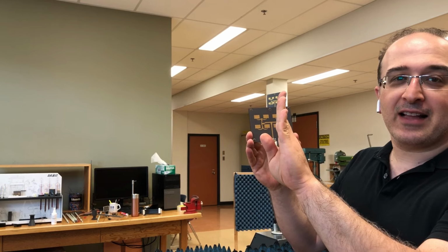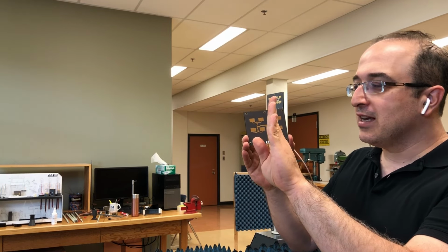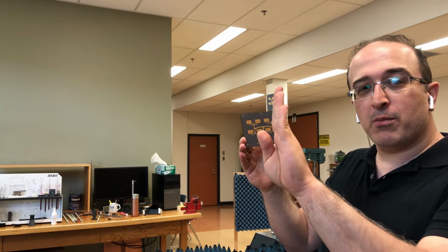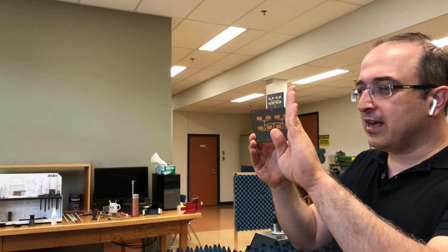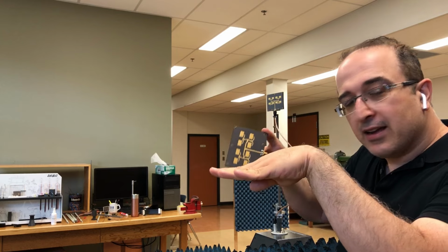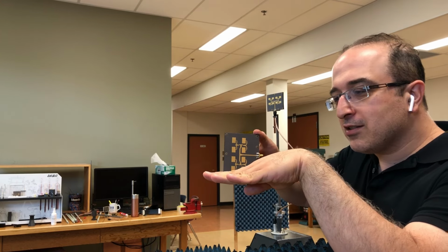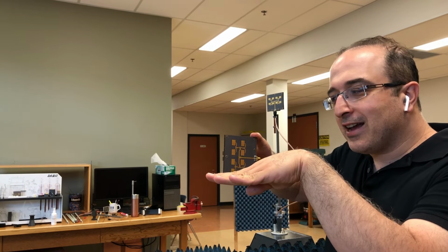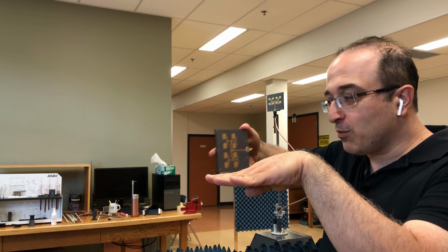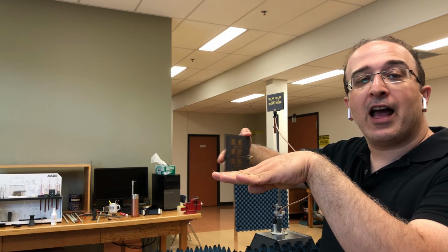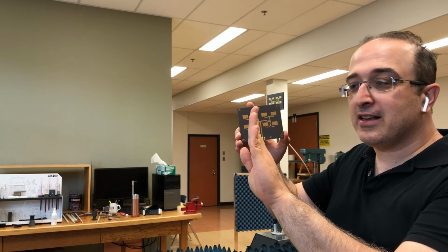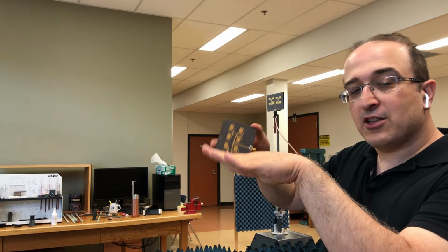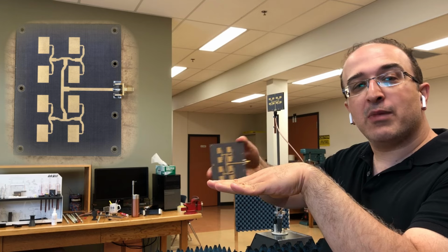So the trick that we always did in this course, to perform measurements in this plane, which in this case is E-plane, is we rotated everything 90 degrees. Now, if I rotate my antenna under test 90 degrees like that, which is supported by the system, now I have my E-plane cut. So instead of mounting the antenna like this, you rotate it 90 degrees.